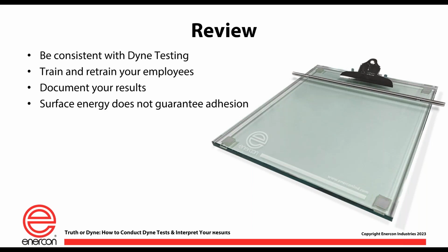It's probably not going to make a difference in your process, considering the variability and some of the diagnostic measuring that we covered today. And then lastly, that the surface energy number that you get in terms of the Dyne level, it doesn't automatically guarantee adhesion. There's lots of other process and material factors that go into that. So keep those things in mind as you move forward here.